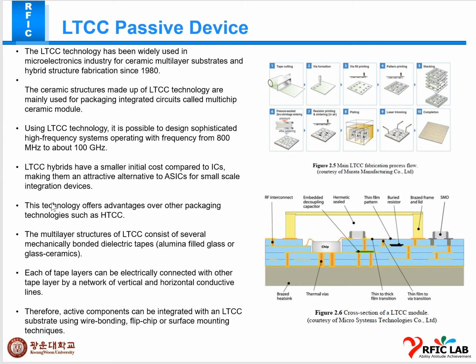In this technology, an advantage over other packaging technologies such as HTCC is the multi-layer structure of LTCC, which contains several mechanically bonded dielectric tapes, and therefore the active component can be integrated with this LTCC substrate using wire bond, flip chip or surface mounting techniques.